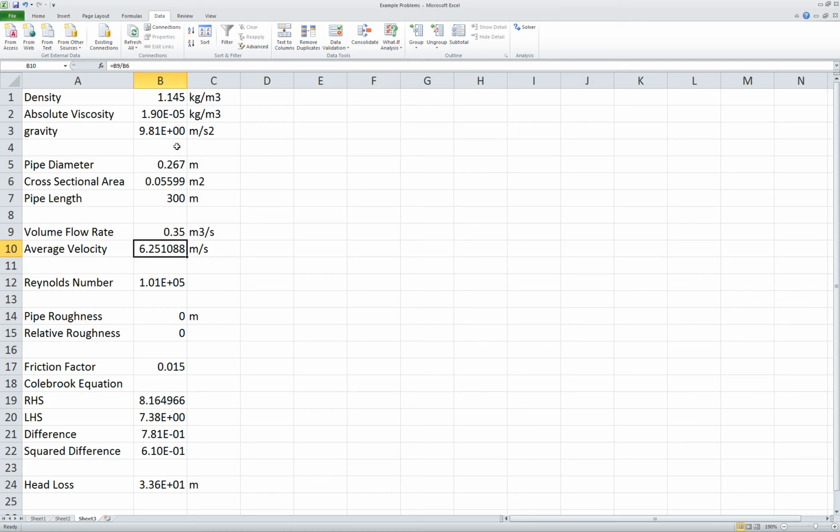So here's how it's going to work. I'm going to guess that since we have a high head loss here, our volume flow rate should be lower to reduce that head loss. So I'm going to guess, let's go to 0.3 and see what happens. So that reduced the head loss to about 25.